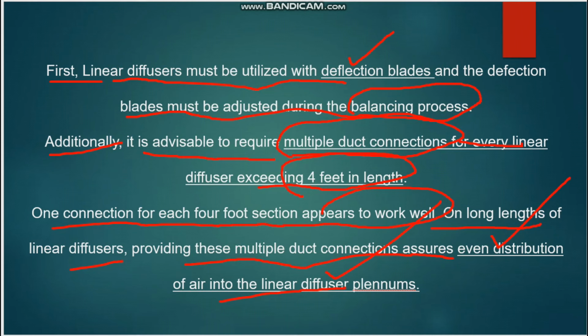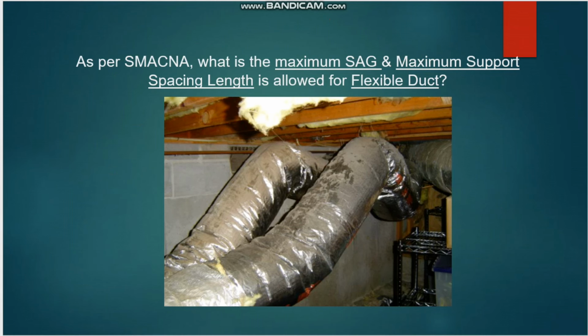So with one duct connection, maximum length of 4 feet must be followed. So as per SMACNA, what is the maximum sag or deflection, and what is the maximum support spacing length allowed for the flexible duct?